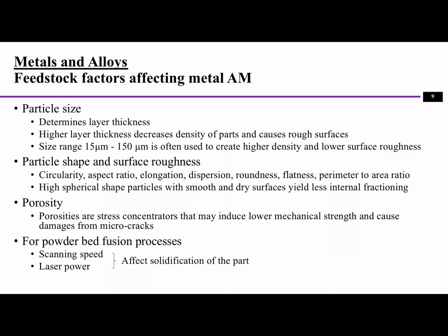If the scanning speed is fast, think about this: the laser melts the powder at one spot, right, and it goes away. After it goes away, it will start to solidify, and then later it will actually come back to the original point, because it's going to scan several times. And then they're going to start to have the edging effect, and that edging effect is going to cause some quality issues.